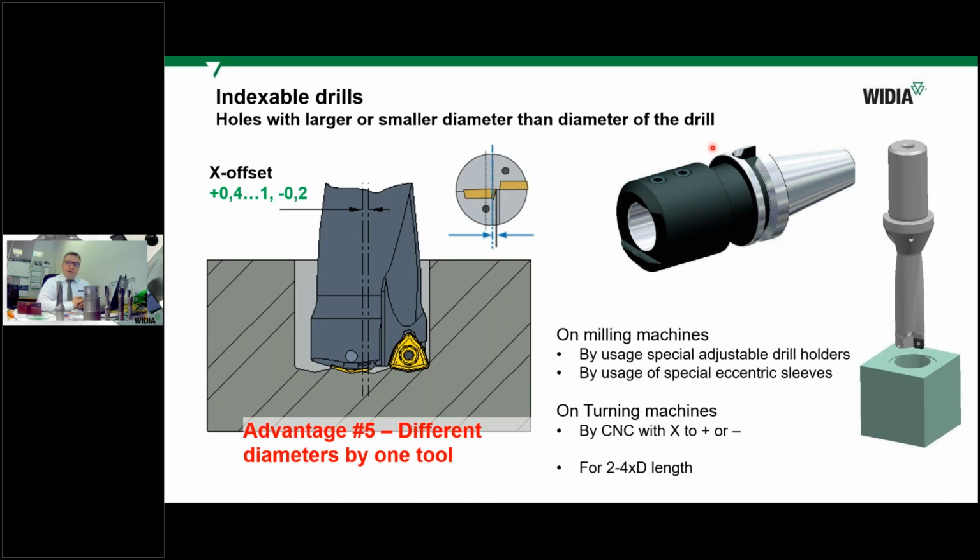One of the ways to avoid this is to decrease the feed, so you can start fighting with a problem when the problem appears, because it may not appear. So maybe there will be no problems. But if there are, decrease the feed, and in future with machining of this hole, decrease the feed.